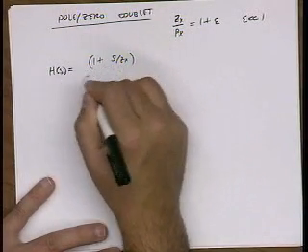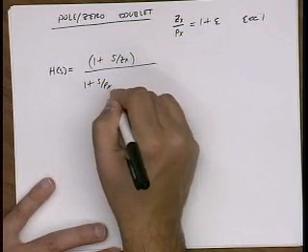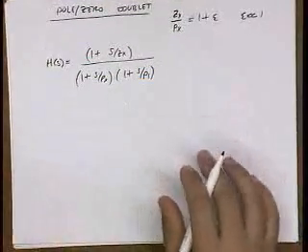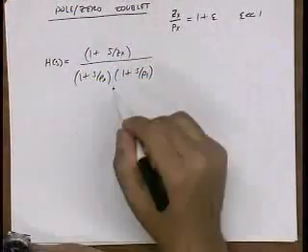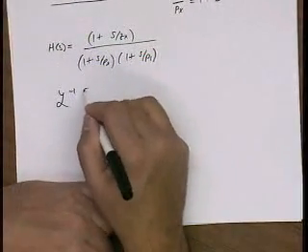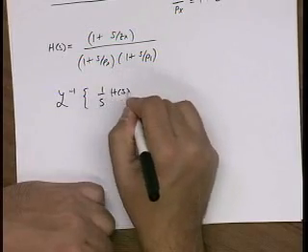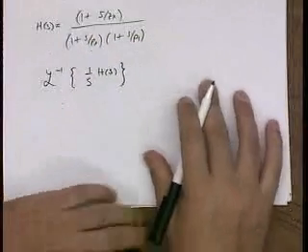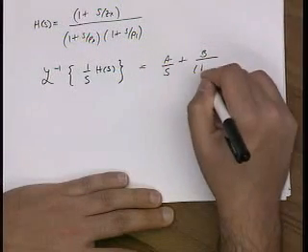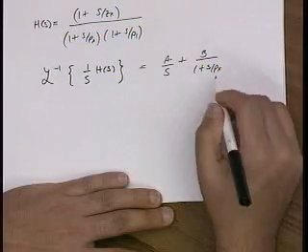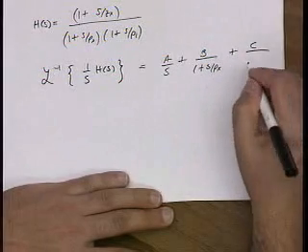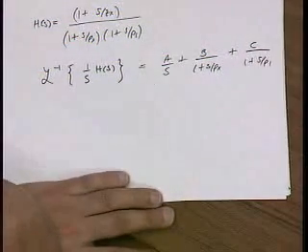is, we have our zero, we have our pole, and we have our dominant pole. So we'd like to see how this pole zero could potentially impact our system. Okay? So just like before, we take the inverse transform with a step input function, and you do a partial fraction expansion. So we have a term that is settling with the time constant of this pole zero doublet, and a term which is the dominant pole time constant.